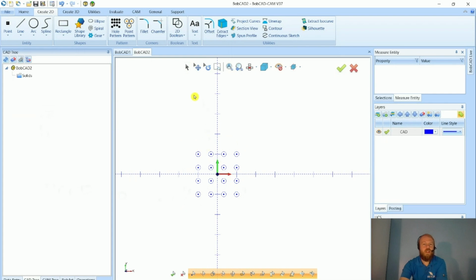So if I go to the top and go to select mode, it's a very important function to use here. Our select mode lets me select any kind of geometry to delete it, to get the summary of the entities I select, to move it around, things like that. I go into my select mode, I can click on one of the holes here, and it selects all of them for me, because technically it is a pattern in terms of geometry.